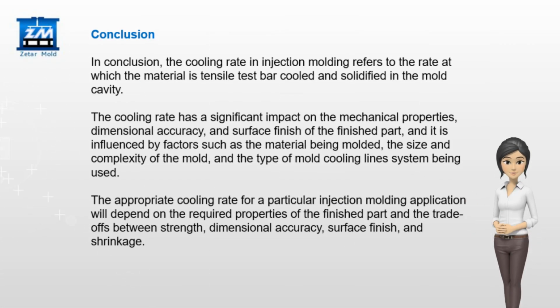Conclusion. In conclusion, the cooling rate in injection molding refers to the rate at which the material is cooled and solidified in the mold cavity. The cooling rate has a significant impact on the mechanical properties, dimensional accuracy, and surface finish of the finished part. And it is influenced by factors such as the material being molded, the size and complexity of the mold, and the type of mold cooling line system being used.